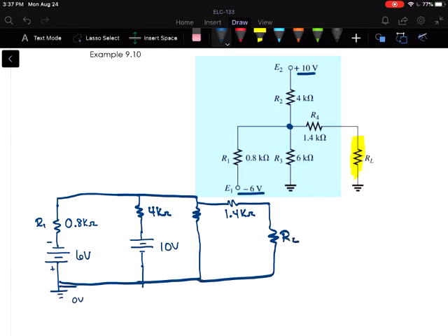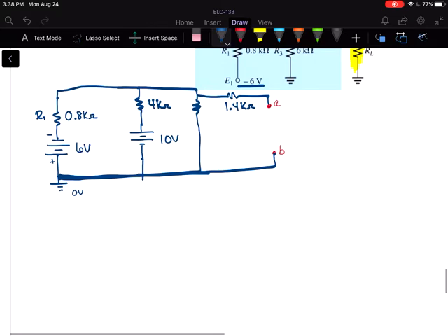All right, so this is basically what our circuit looks like. And we want to find the Thevenin equivalent circuit for everything external to the terminals A and B right here. So what I'm going to do first is remove the RL. Remove the RL, and then I'm left with just my terminals A and B. So step one, of course, is to find our R Thevenin.